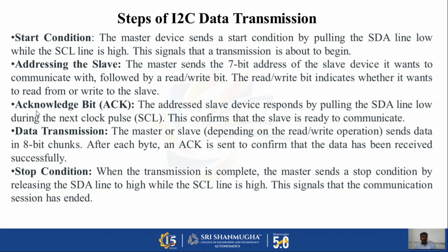The next step is data transmission. The data is transferred in 8-bit bytes. After each byte, the receiver sends another acknowledgement signal to confirm successful reception. This process continues until all data has been transferred. Finally, the master generates a stop condition indicating the end of the communication.